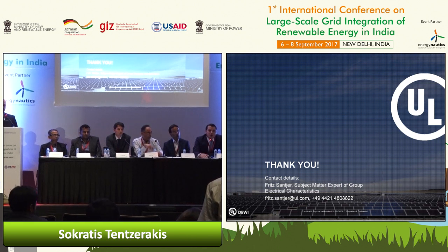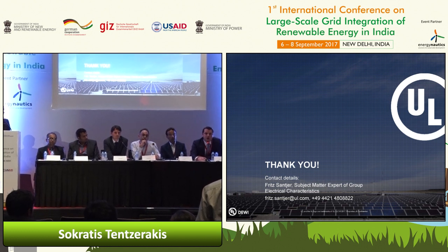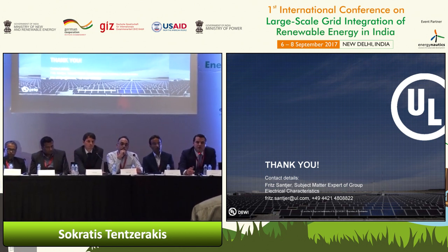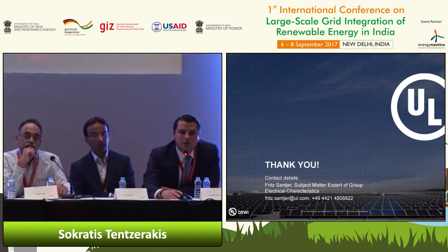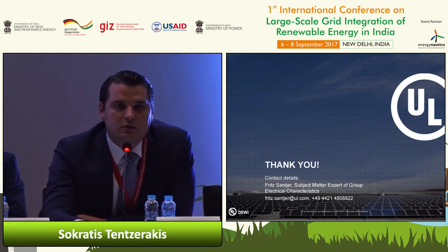And what we do in Germany is that, based on such type testing, we use the measurement data in order to validate a simulation model. And the project-specific evaluation of a wind farm will only be done by calculation and by simulation. This is our approach to be cost-effective, because you do testing once, spend a lot of effort in developing a simulation model, like also Eckhard Tröster just said. It's quite complex, it must be very accurate, but once you have the model, you have the potential to calculate any kind of constellation that comes to a project-specific installation.